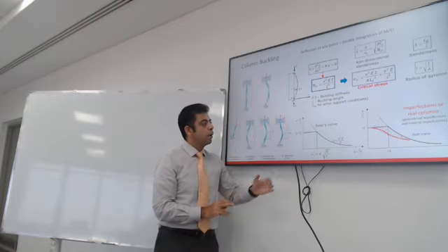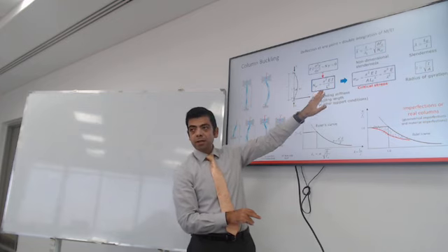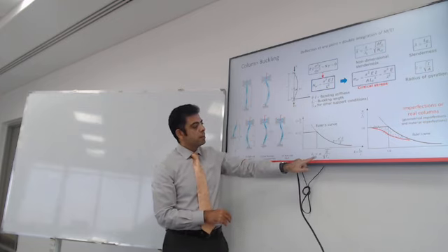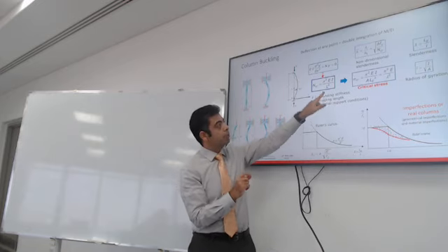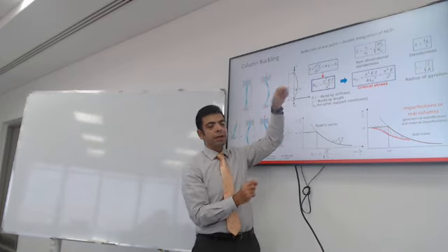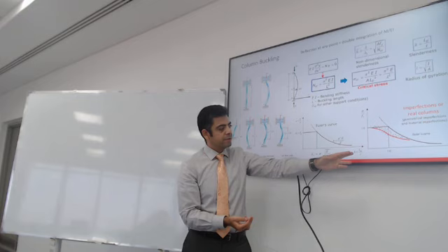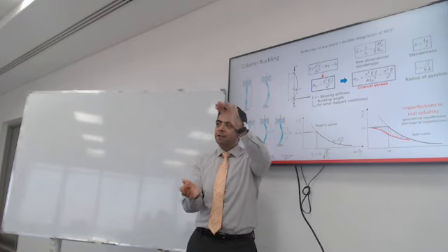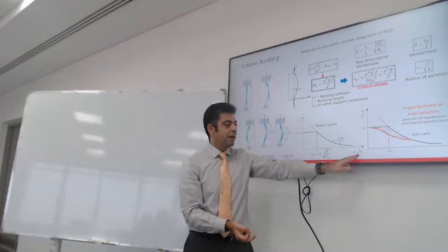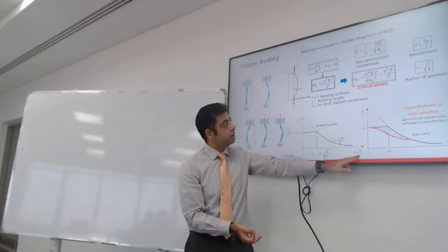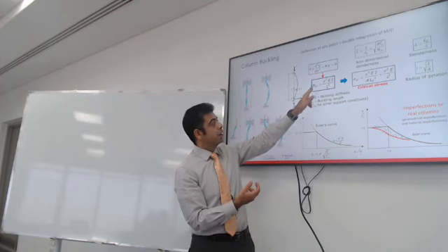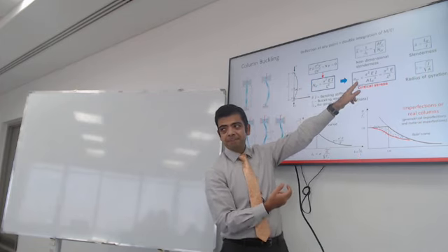All right, so if you plot this equation with the factor lambda. Lambda represents the only variable in the critical load. It's the ratio between the effective length and the radius of gyration, which is a way to translate the load into stress.